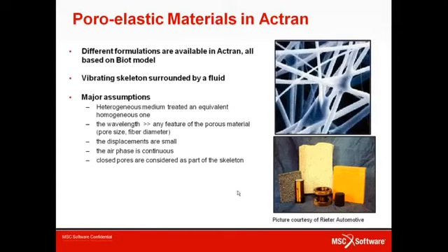The Biot theory is based on several assumptions. First, the heterogeneous medium is treated as an equivalent homogeneous medium with a solid phase and a fluid phase that are interacting with each other. The wavelength is assumed much greater than any feature of the porous material, such as the pore size or the fiber diameter. The displacements are assumed small so that the theory of linear elasticity can apply. The air phase is continuous and closed pores are considered as part of the skeleton. And as such, any effect related to the movement of air inside those closed pores is not taken into account.